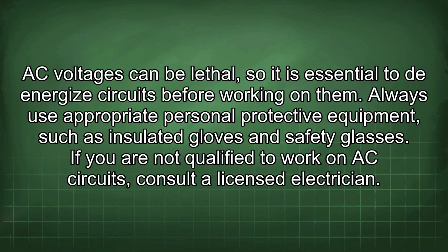AC voltages can be lethal, so it is essential to de-energize circuits before working on them. Always use appropriate personal protective equipment, such as insulated gloves and safety glasses. If you are not qualified to work on AC circuits, consult a licensed electrician.